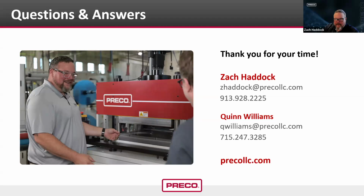There's a lot of variables going on when we are setting up these presses: die wear, ejection rubber wear, all of the above. The fact that maybe we just miscalculated a number. If I've got that 20% there, that usually will cover me in all instances, especially if it's a hot job and I've got to make sure I get it out the door.